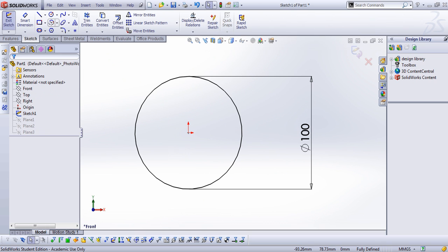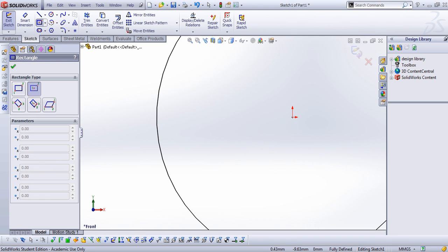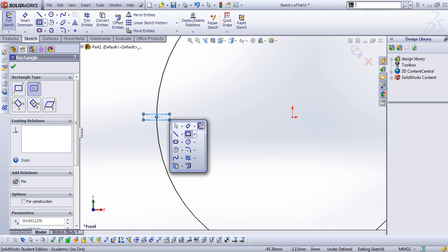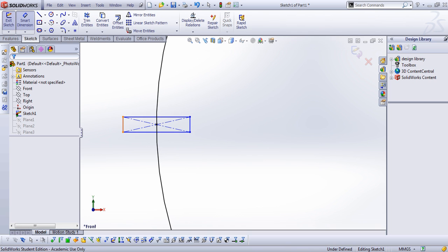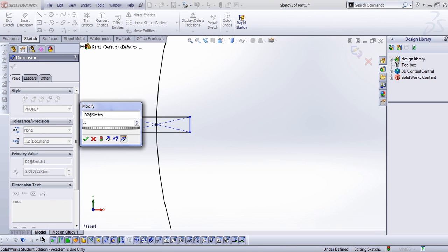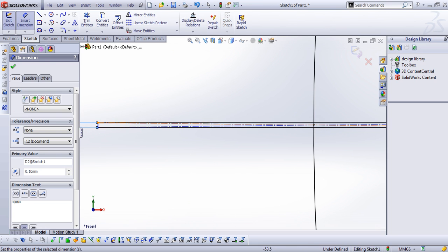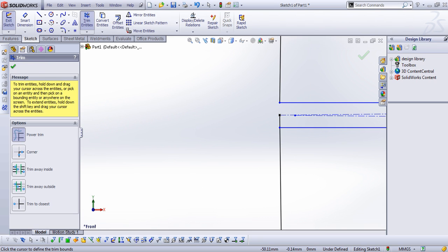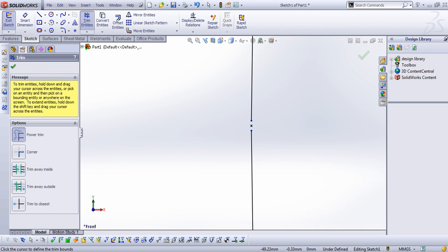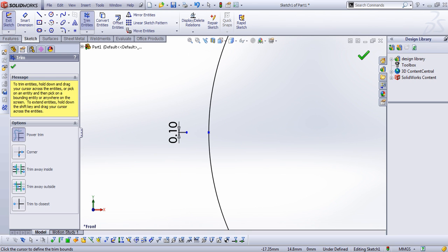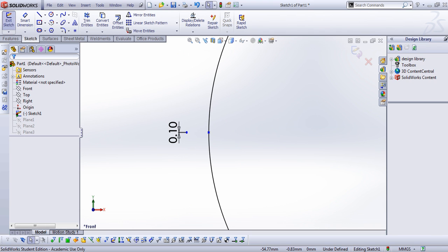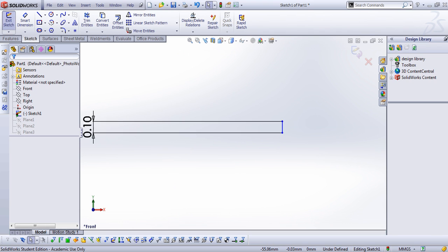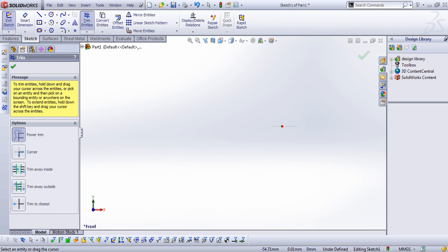and I modify the plane, so I will make a rectangular shape right here, and then I give a very small distance, so I give it 0.1 millimeter, and then I do a simple cut here. Okay, this is done. Oh, actually, this has to be done here as well. Let's just delete this one too. Okay,